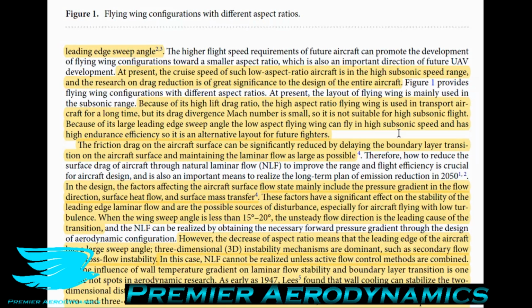The reason why is because up at 30,000 feet, you have very few disturbances. Down at sea level, we have a lot more disturbances. There's a lot more around creating these disturbances. So why are disturbances important for Reynolds numbers? The reason is that, in laminar and turbulent boundary layers, the disturbances create turbulence. If you have a big enough disturbance, that will then break down in 3 dimensions and create a turbulent flow.